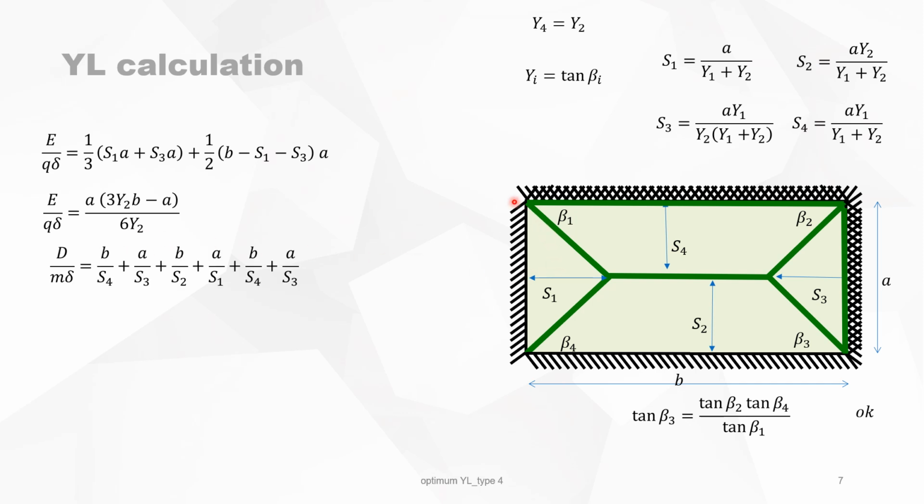We fill in the different variables and we obtain this expression. Now we calculate the work done by the internal forces, divided by the bending moment and the unity of displacement. We project the bending moment m to the axis of rotation. So we got B, the length of the axis, divided by the angle of rotation, which is delta over S4. So we have B over S4.